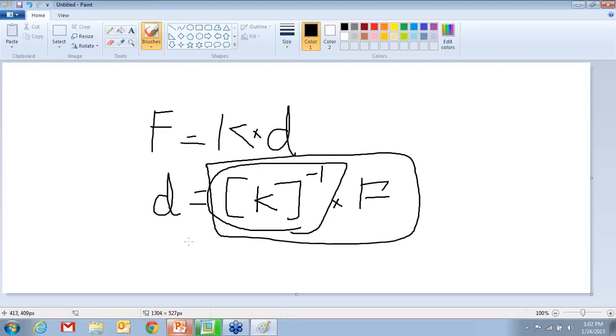That is why anytime you call tech support and ask them, hey, my part wouldn't solve, they'll say, oh, you need to refine the mesh. So basically you're thinking like a programmer. What are you doing when you refine the mesh? You change the numbers inside the K matrix. So with the same constraints, with different numbers, maybe the K matrix is invertible. You see what I'm saying? Whenever it says insufficiently constrained, it doesn't mean that your constraints are wrong. In the mesh, they don't detect those constraints.